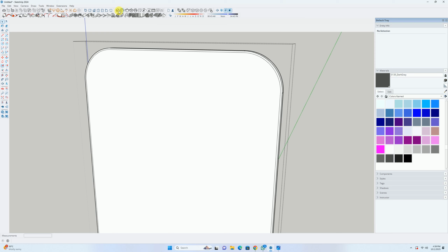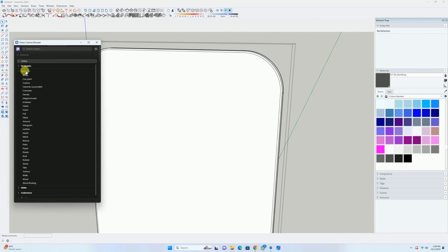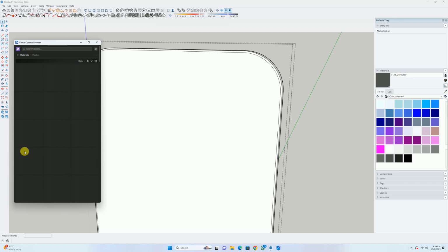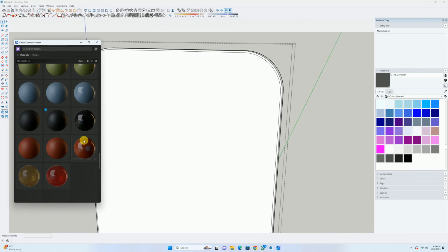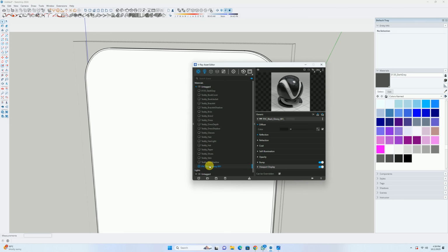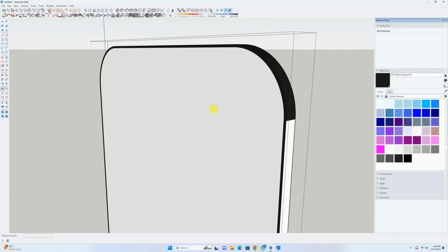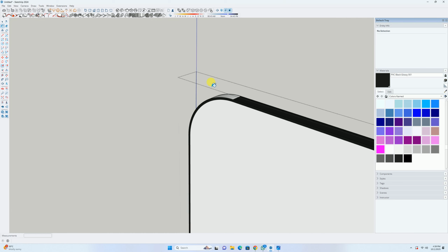Then I'm going to specify its color as glossy black material. Okay. So we are going to the Cosmos, and in Cosmos we'll go to this material feature, and in the material tab we'll go to the plastic material option, and here we'll get PVC black gloss. So I'm taking black glossy material. I'll import this material. Okay. Then we'll go to the V-Ray material option, and from here we'll select our design material and we'll specify this frame as glossy black.